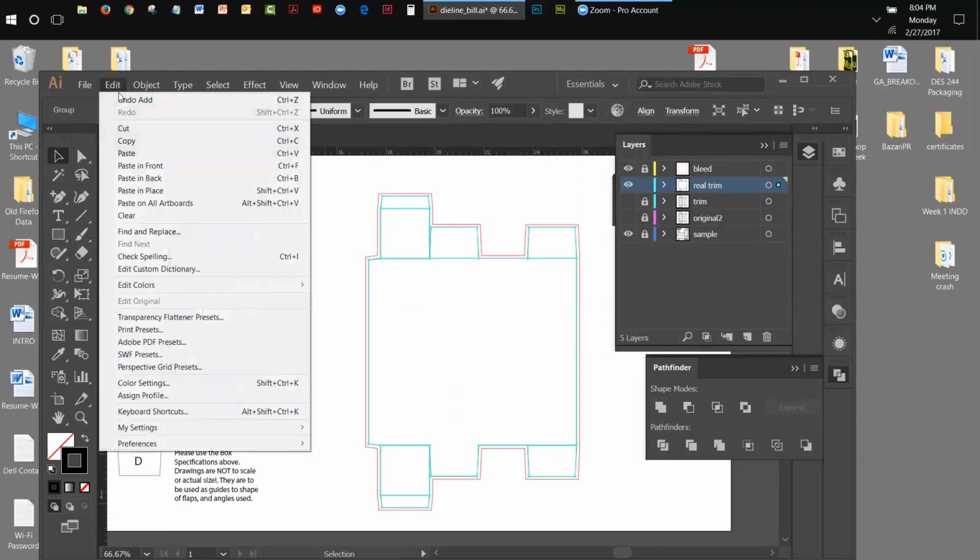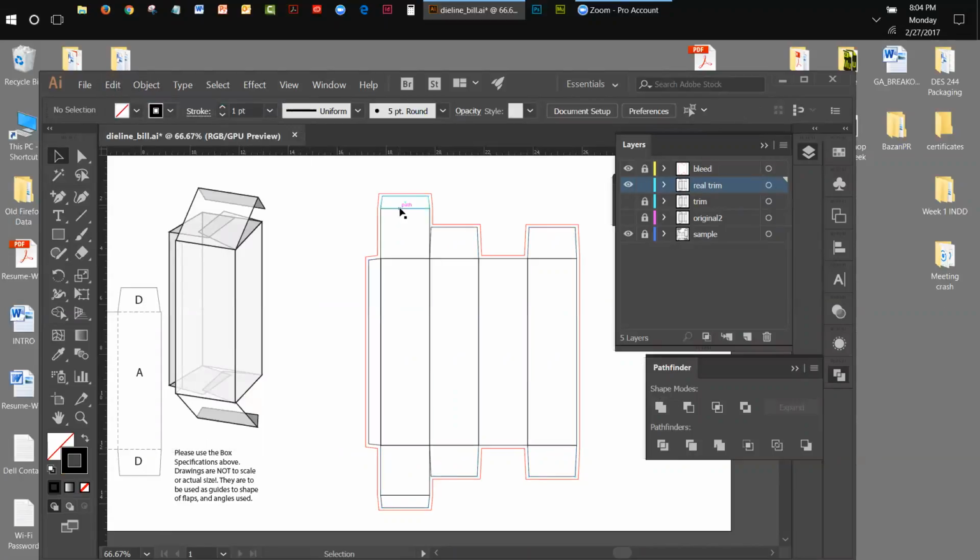And again, I got the same problem with this. So I'm going to go Edit, Undo, and I'm just going to select these two right here, and I'm going to move them down 1 pixel. And then this guy here, select him, move him down 1 pixel. That's the down arrow. This guy here and this guy here, 1 pixel down, okay? It's not going to hurt anything, just moving it ever so slightly. And actually, I can do this in one shot. I'll do all these guys 1 pixel up, and then this guy down here, 1 pixel up. Now, that should do it. Let me click on that, and let's try uniting them now. Boom, look at that, perfect, okay?